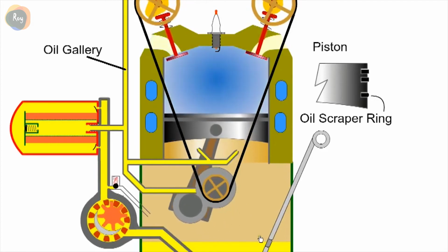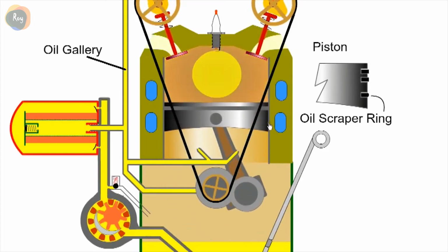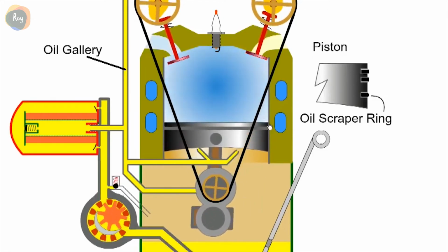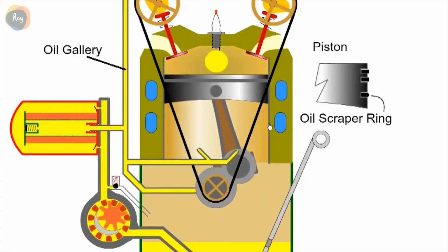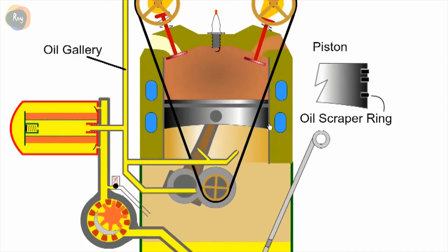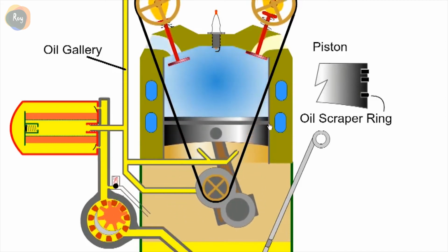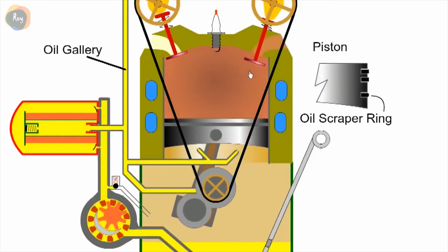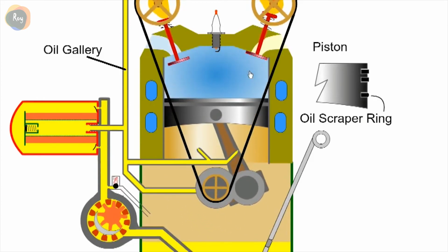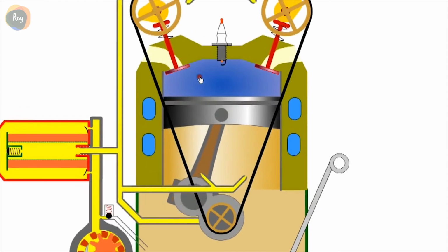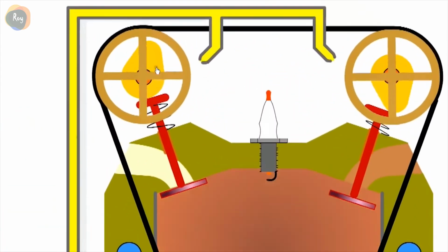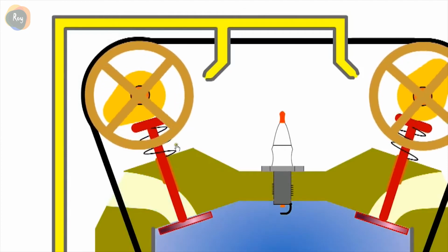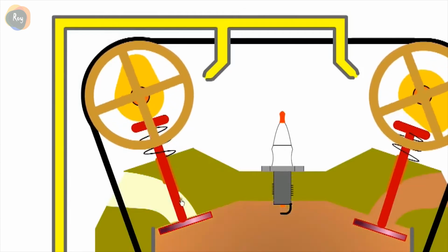The oil will provide a sliding seal between the piston ring and the cylinder wall. The seal helps maintain cylinder compression during the compression and combustion cycle, preventing blow-by. It will also prevent oil entering the combustion area when the cylinder is under negative pressure during the intake stroke. Oil is also pumped to the camshaft and valve springs. An oil seal at the top of the valve guide prevents the oil from being drawn into the engine.